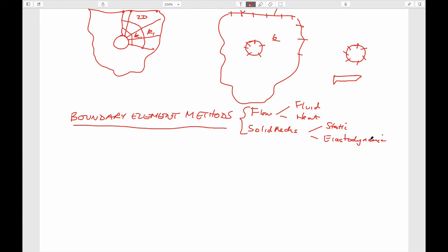For wave propagation and transient problems, certainly steady state problems are very easy to do. And I suppose it might be worthwhile mentioning that steady problems are easiest to do. Because if you start doing transient problems, or problems such as advective transport, then all of a sudden you actually have to distribute elements within this domain. And so, to me, you lose many of the advantages of this in being able to get away with a really easy mesh.